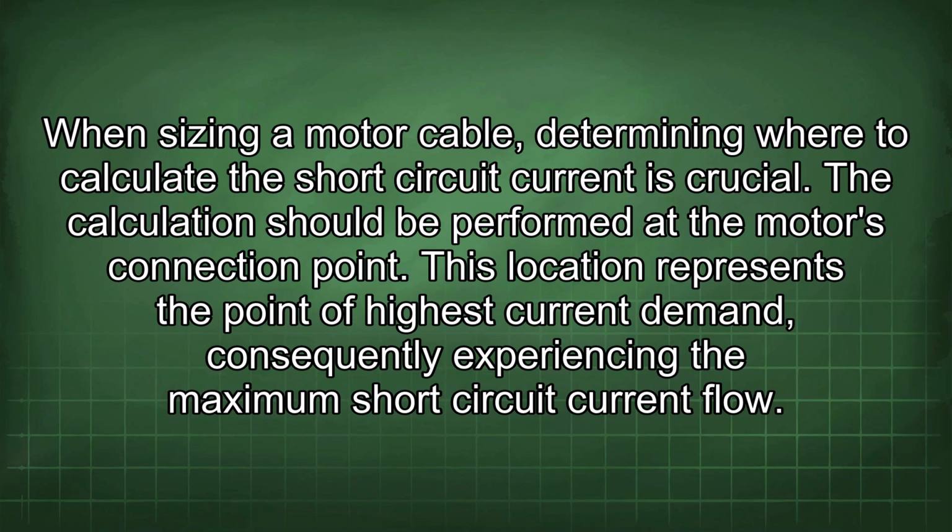When sizing a motor cable, determining where to calculate the short-circuit current is crucial. The calculation should be performed at the motor's connection point. This location represents the point of highest current demand, consequently experiencing the maximum short-circuit current flow.